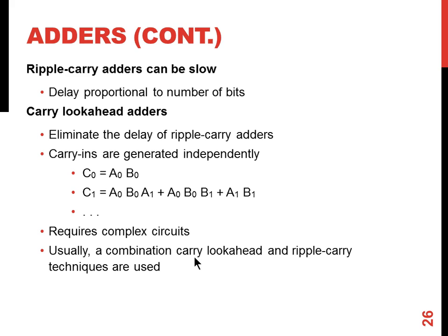Ripple carry will give me less area. Carry look ahead adder will give me faster speed but more area. You can mix and match the adder implementation for various stages of the design.